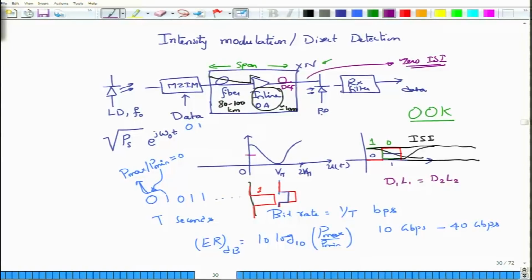One source is the load resistor that we keep, which will have its thermal noise, which we have talked about, and there will also be what is called shot noise because of the fluctuations of the source itself and the fluctuations in the way these semiconductor photodiodes actually work.